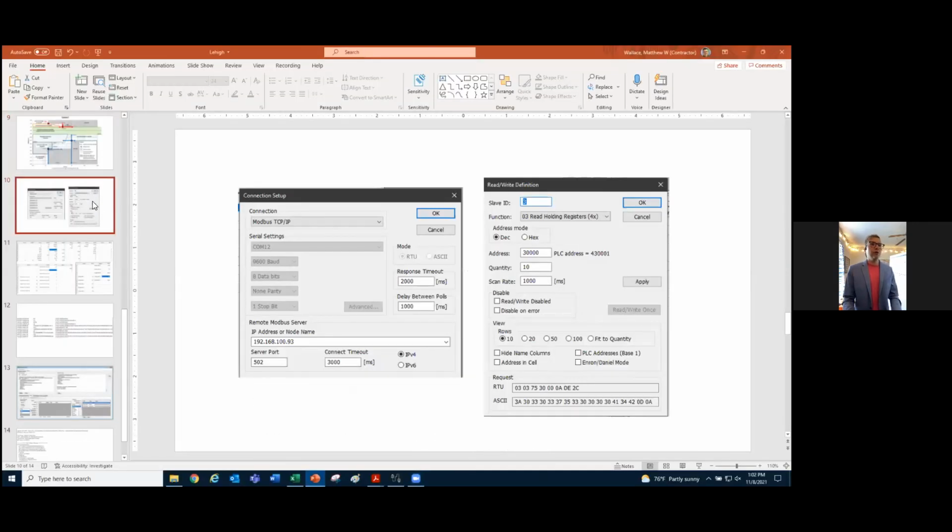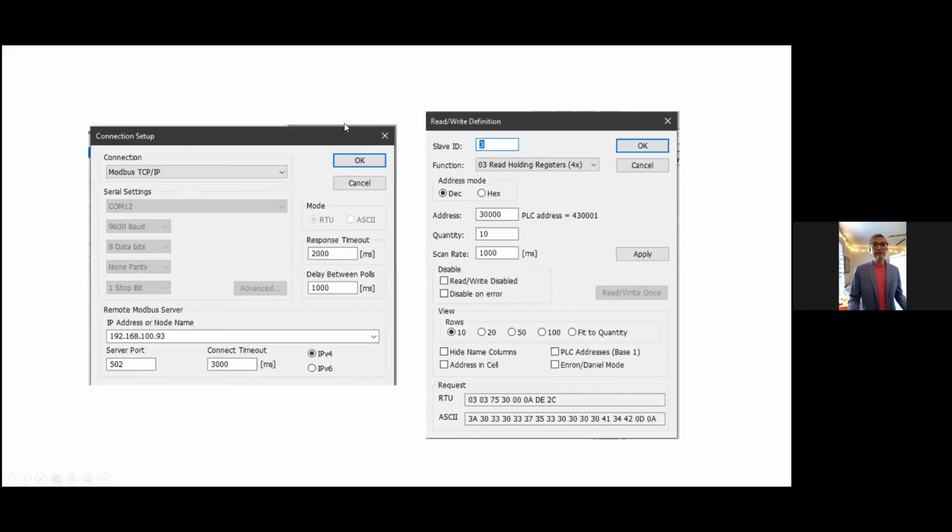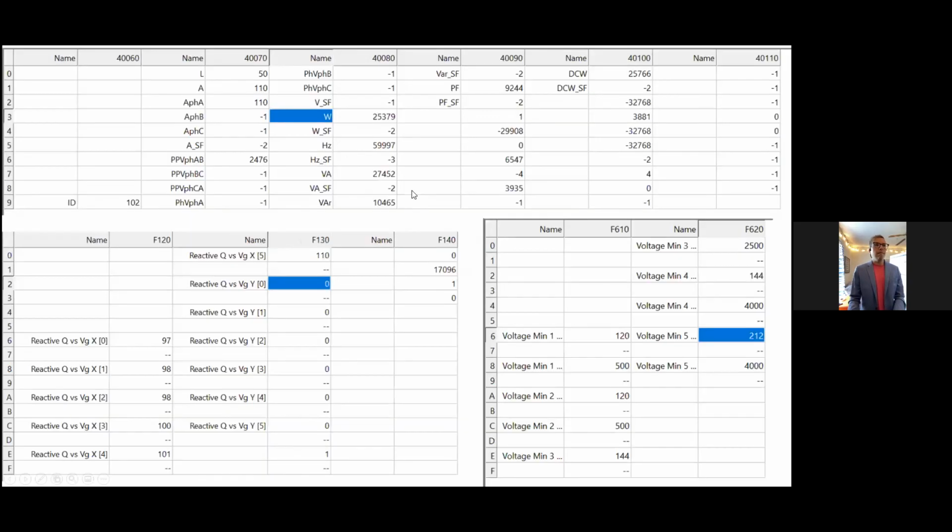So I'll show you really quick what a Modbus interface looks like on an inverter. These are screenshots from an application called Modbus Poll. This is just a really simple Modbus Master. It's a device that you would plug into an inverter's communication interface. You would set certain settings here. Hey, go to this IP and look at these Modbus addresses at the scan rate or whatever it is, right? You can adjust all the stuff as you need. And then there are 3 different screenshots in this window to show you what it looks like.